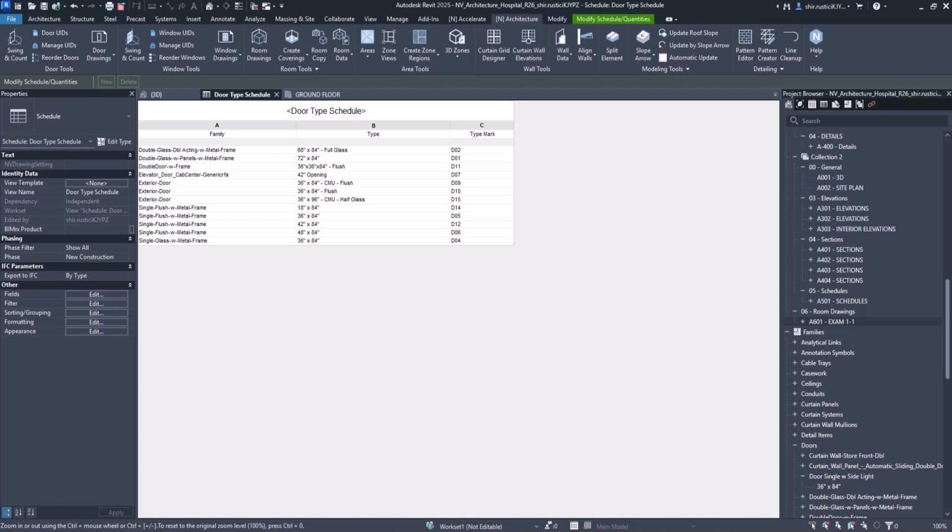The other improvements that I will show are the optimization of placement of the dimensions and tags, the use of non-flipped or mirrored doors, so using the original swing direction of the door when selecting which doors to create the views from, and lastly, enhancing the view scale so that you can use any view scale when creating your door and window drawings. Now let's create our door and window drawings and see this in action.